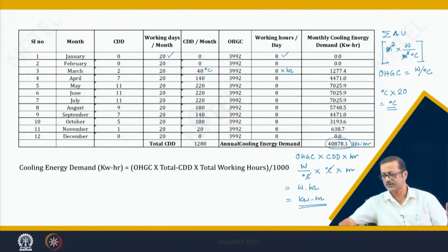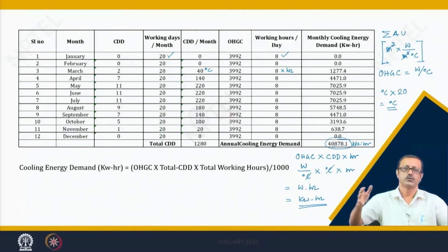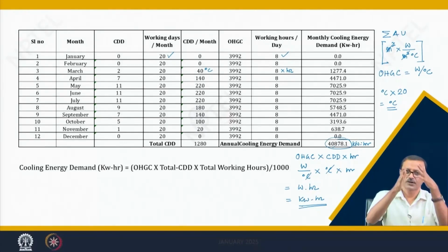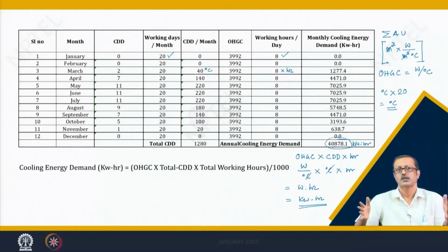If you remember the last lecture, we calculated for a particular solar radiation and temperature for a particular hour, and now it is solved for a year, but of course, it is approximate. It gives you only the conductive kind of treatment. It is not taking care of your radiation heat, because SHGC is missing, solar air temperature is missing, no data of the solar radiation is there. We will see that later.